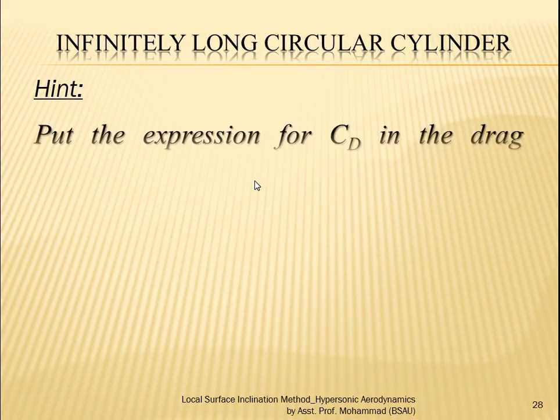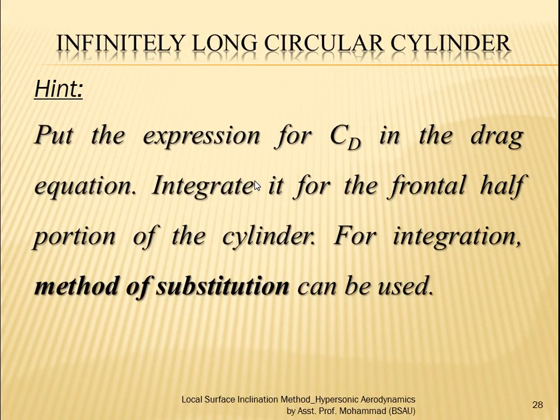In the entire analysis of the long cylinder, basically two things we should consider. One is the accurate measurement of theta, which you put into the equation of Cp, and then the elemental area on which it is acting.